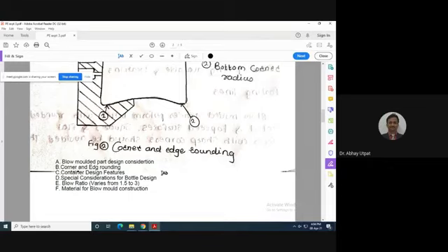I repeat this once again. I am explaining point number D, special considerations. So vertical strength. The part is kept on some machine and strength is measured. Once 1 or 2 samples perform okay, only then are the remaining parts manufactured in the mold. Otherwise, if you find that some problem is there, then there will be modifications in any of the parts given above. Maybe the material, maybe a change in thread, maybe the fill point, maybe a little reduction or increase in weight. Such trial and error may be carried out.